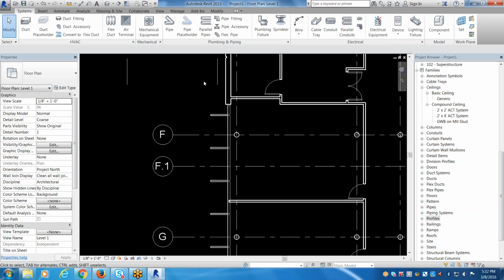And it gets tricky because Revit families are also reusable, right? Meaning, when I create, let's say, this duplex receptacle, I want to be able to use it in all my projects, whether it's a 2014 project, a 2015 project, a 2016 project. That receptacle is good for all of them, right? It's a receptacle. So when we create new families, we create them in the oldest version of Revit. That way, if I need it in 15, I can copy it out and upgrade it. But if I created it in 16, I couldn't use it in 14 or 15.